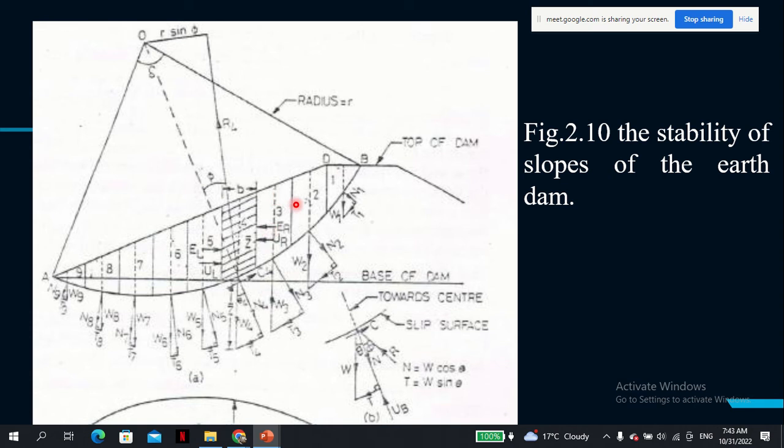You find the area, because now this would be a regular shape, like a trapezium whose area you can find easily. Based on the area, you assume a unit weight in the direction perpendicular to your eyes, so that means the area would be the volume basically. And then you resolve, because the self weight will have a normal component in this direction and a shear component, and then you sum all of them together.